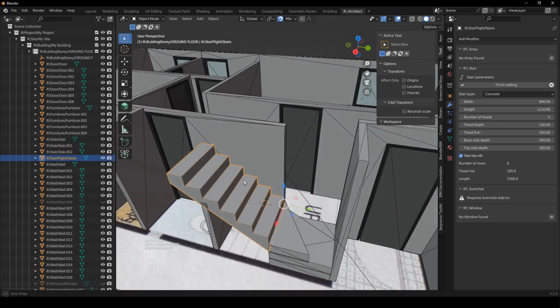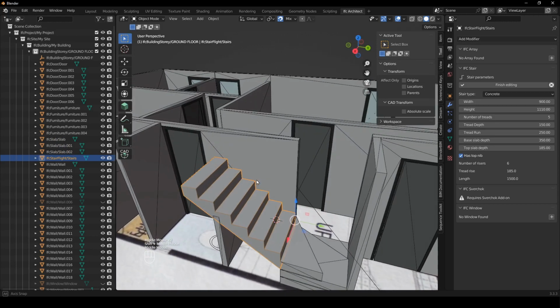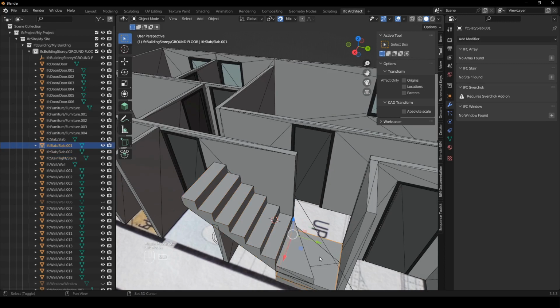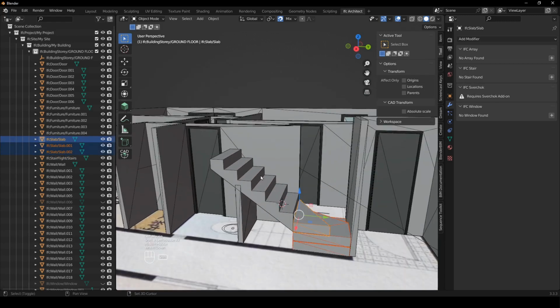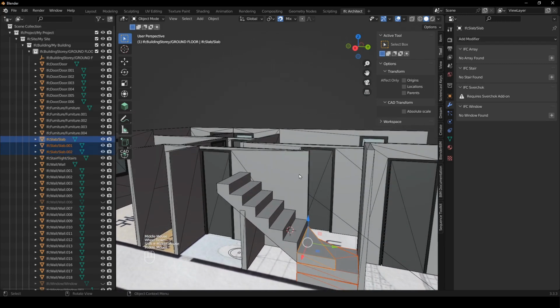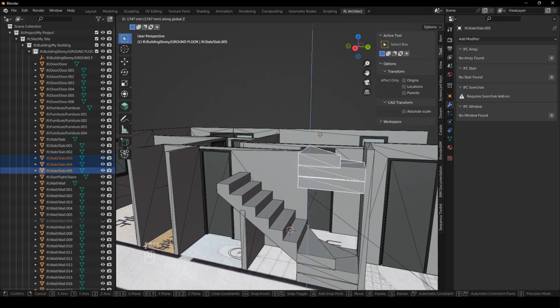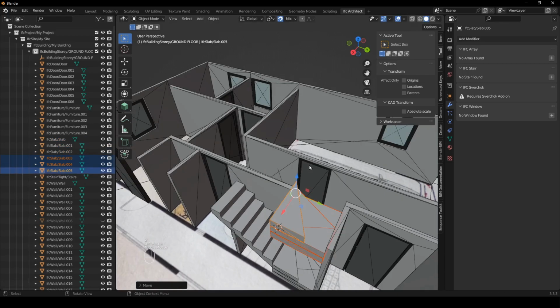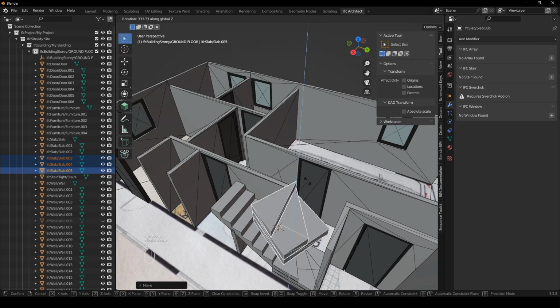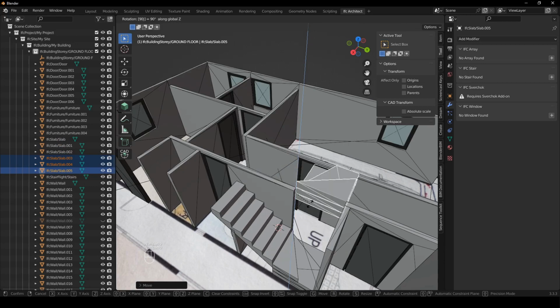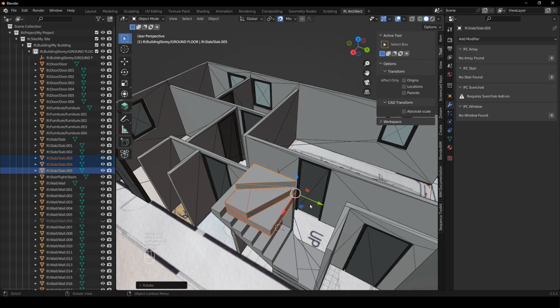And then we just need the winders on the end. So we can select these 3, and the geometry is not going to really make a lot of sense, but in plan it will. And we're going to say Shift D, Z, and bring it to this outside height. And we're going to say rotate Z that way, which is 90. Oh, it's -90.